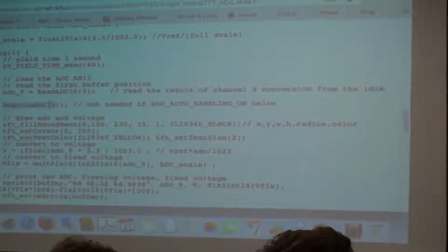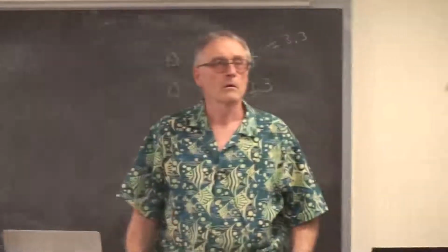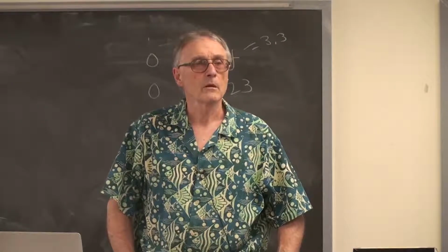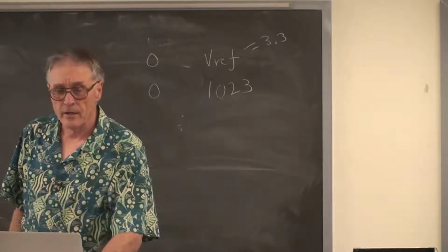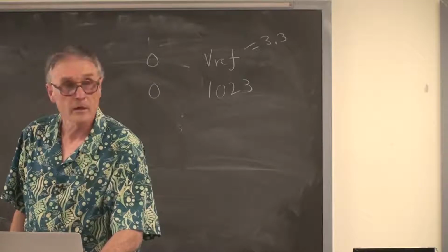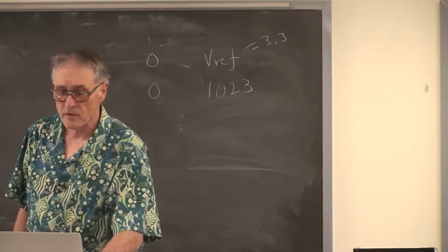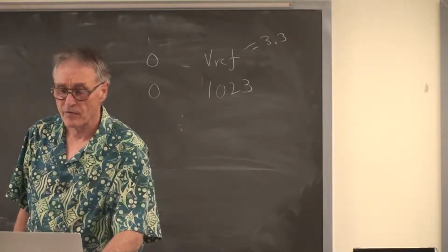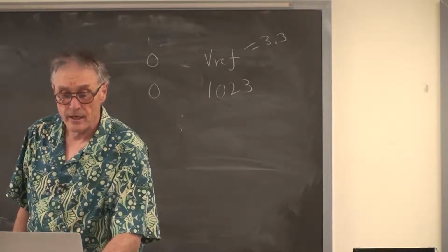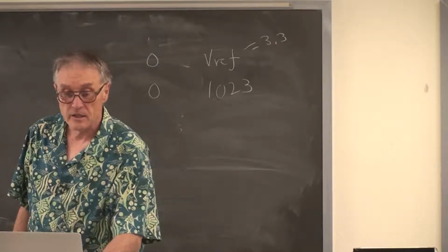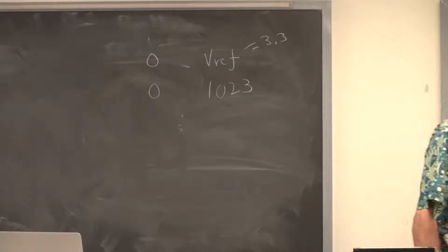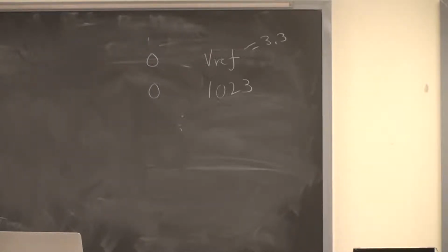So after the acquire and the conversion, the converted value is stored somewhere that you're reading from. It is stored in the buffer right here. Stored in buffer 0. So the output of the ADC goes into buffer 0. And that is why we're reading 0 right there. It's not channel 0, it's buffer 0, which was loaded with the data from AN11.